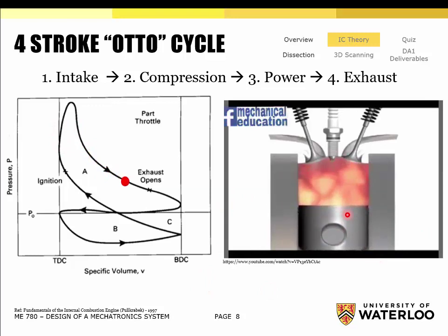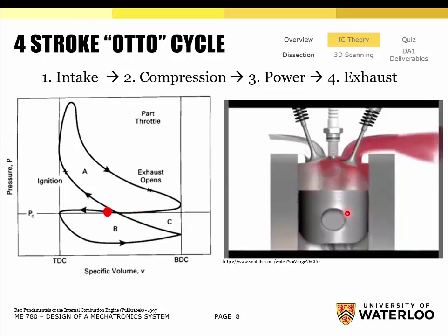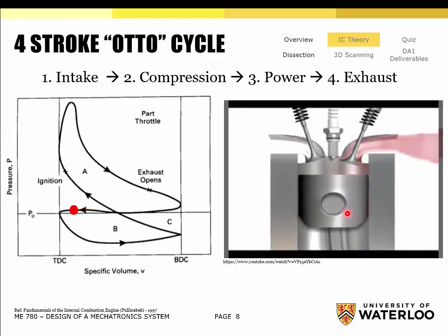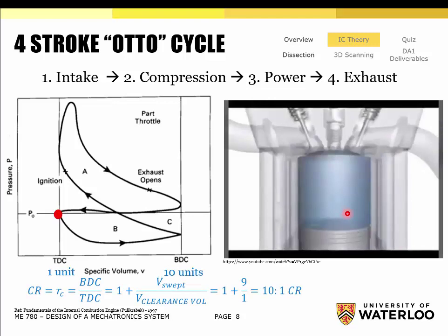As the piston moves back down, because the pressure and temperature are so high, this is when we're really pushing on the piston. Okay. So this PV diagram, which you see here, the areas that are enveloped in each of these loops can tell you how much work is being done, because work is just force times distance. Okay. What we have here is volume, which is effectively distance because the bore size is constrained to be the same. The distance is the only thing that's influencing the volume.